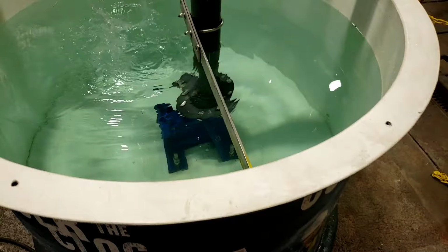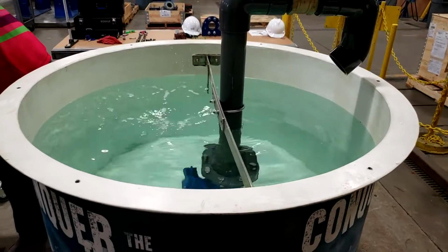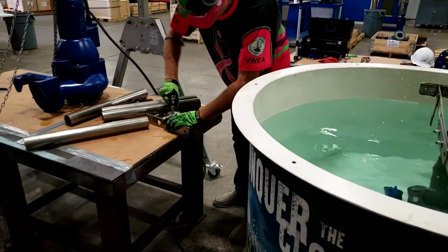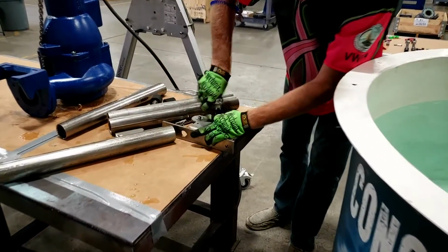Prior to removing the guide rails from the wet well, you must shake them 3 times inside the wet well to ensure all or most of the water is out of the rails prior to taking them out of the tank. Remove the 9/16 nut on the guide rail flange to loosen the rubber compression fittings from each rail so that you can remove the guide rails.